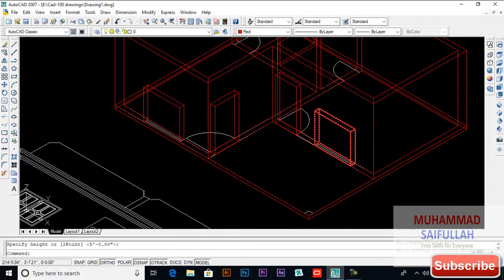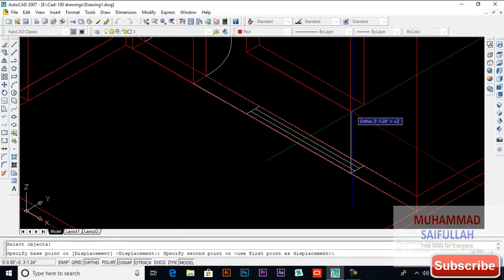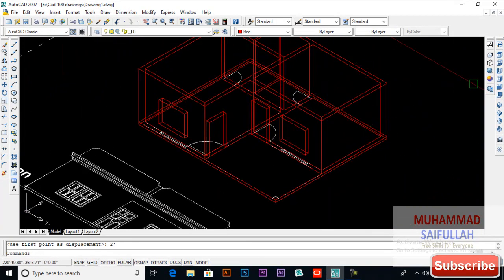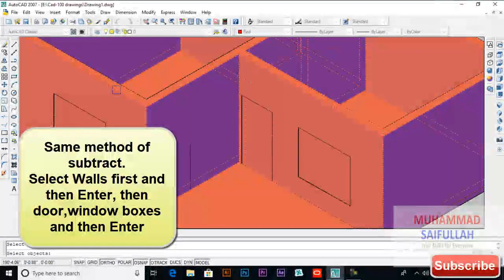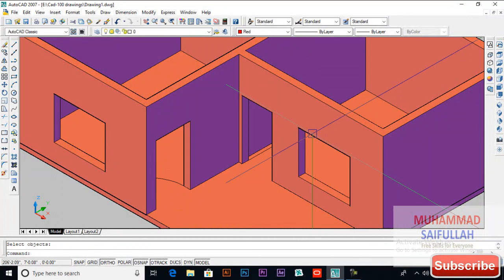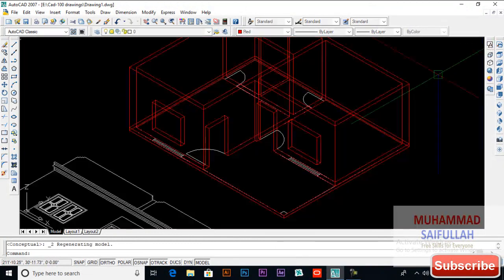Now I will move these two objects from their base point. I will give it a height of 2 feet. So I will move it, select both of these objects, press enter, and from this point I will give it a direction on the z-axis and will give it a height of 2 feet. Now I will subtract it. SU subtract, select that wall first, then enter, and then select these objects. So that's how we subtracted our doors and windows.